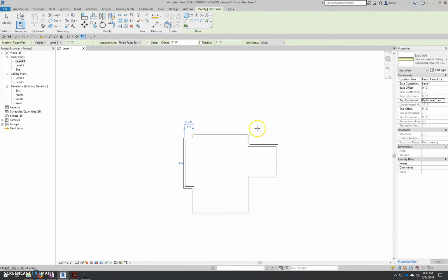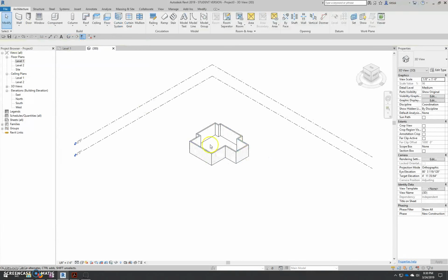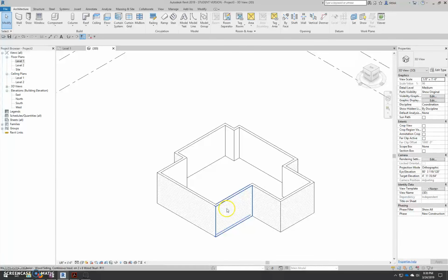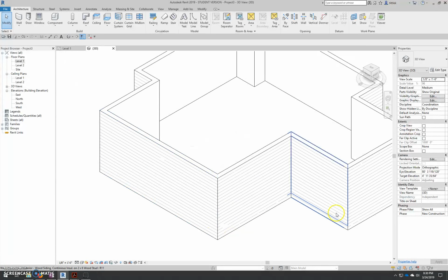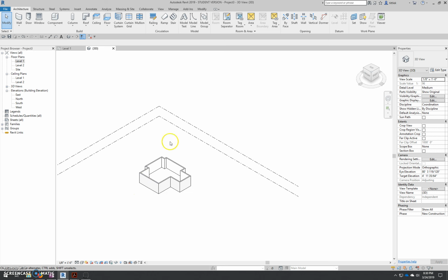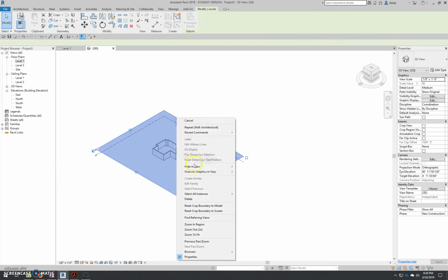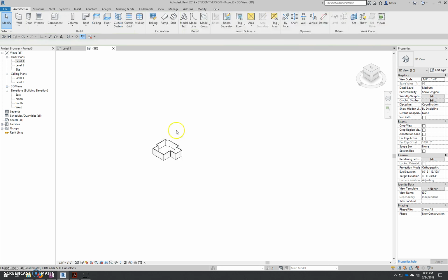And finally, the last part of my Revit creation method, I like to go to my default 3D view to see that I did create what I expected, walls that go up to the second floor. You can also see in my 3D view that those walls do indeed have that 6-inch line pattern for the siding in this view. Now, just like last week, I don't want to see these levels, so I'm going to right-click, hide in view by category, and those go away.